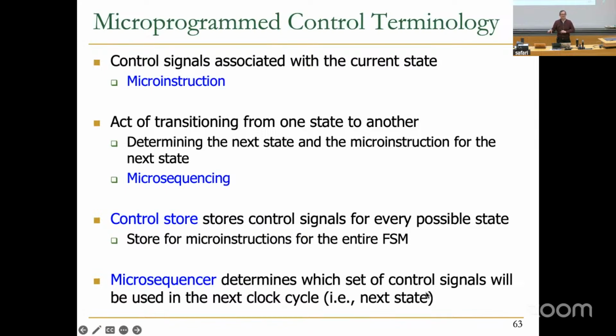In a sense, what we're doing as hardware designers, after we design the data path and the control signals, if you think about it this way, you're microprogramming a machine. You're not programming it at the ISA level, you're programming it at the control signal level. And the program is really stored in that finite state machine. Your finite state machine describes your program, and your control store stores your program, and you sequence from micro-instruction to micro-instruction. Each micro-instruction determines the control signals in each state.